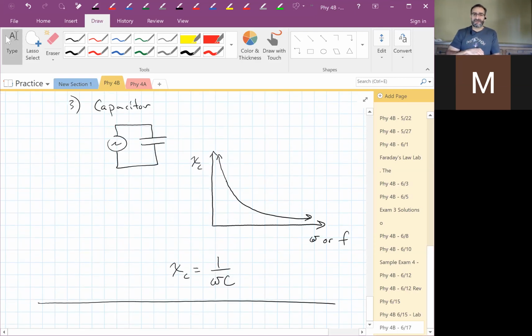We're saying, what does our circuit look like when the frequency goes to zero, when nothing's changing? And this is a battery, a sort of DC circuit with a switch, right? The instant the switch closes, that's like an infinite frequency. It's really high frequency. We went from nothing to something. At that instant, it's a really big frequency.